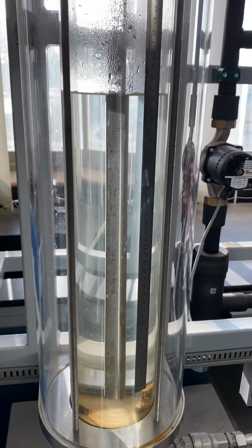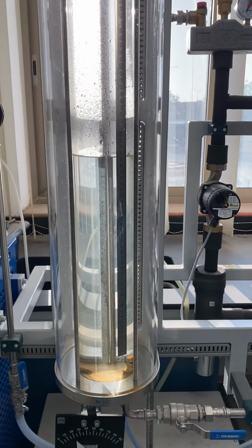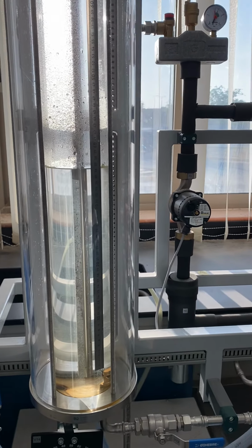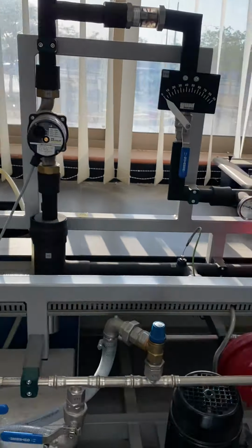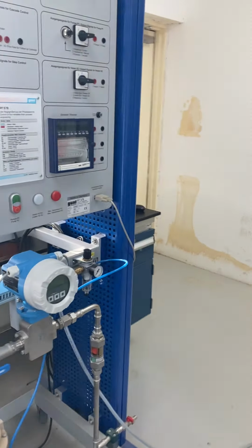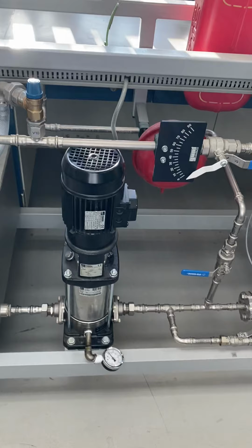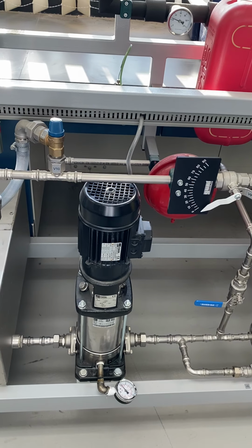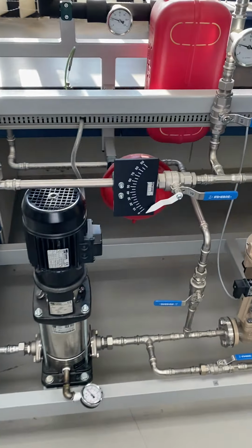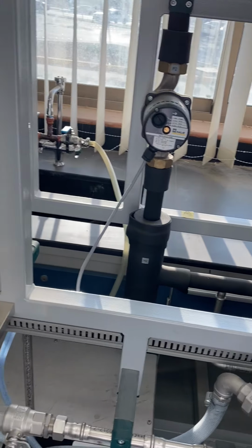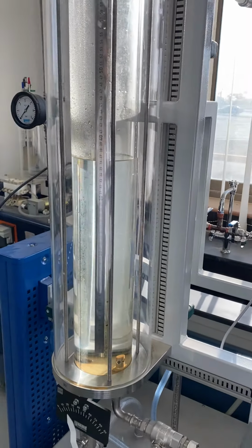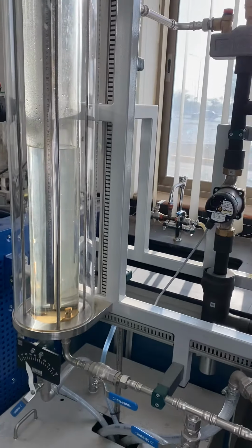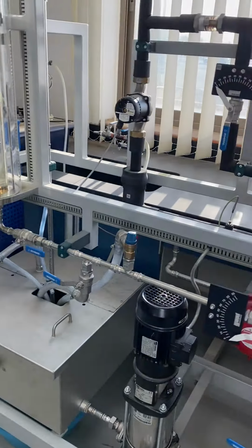We will see that as a result of the drop in water level inside the tank, the controller will increase the output signal, and that will cause the pump to run at a higher speed. It will increase the pump speed to increase what? The inlet flow rate, so it balances with the outlet flow rate and the level returns to the required set point. We will see that, inshallah, in a minute.